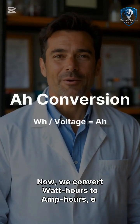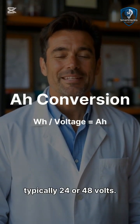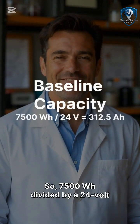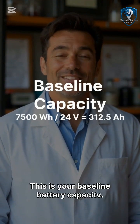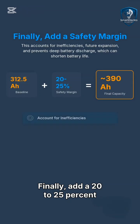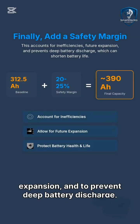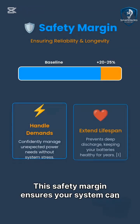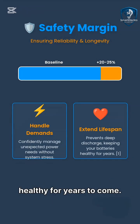Now, we convert watt hours to amp hours, or Ah, by dividing by your system's voltage, typically 24 or 48 volts. So, 7,500 Wh divided by a 24-volt system gives us 312.5 Ah. This is your baseline battery capacity. Finally, add a 20 to 25% safety margin to account for inefficiencies, future expansion, and to prevent deep battery discharge, which can shorten battery life. This safety margin ensures your system can handle unexpected demands and keeps your batteries healthy for years to come.